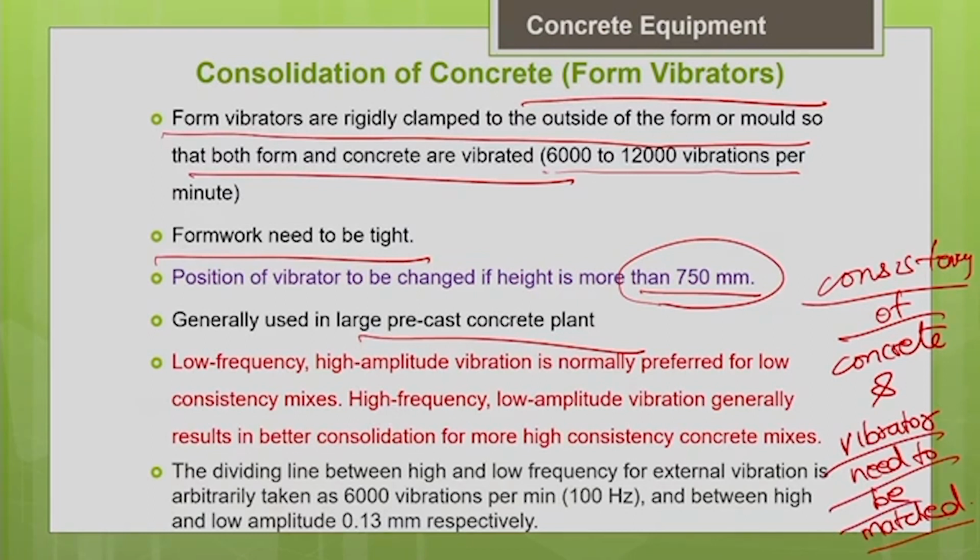Another important thing is the frequency and the amplitude of the vibration needed. That also depends upon the consistency of your concrete only, because that is going to govern the efficiency of your vibration. Basically, for dry mixes which have low consistency, obviously the spacing between the particles will be more, because there will be a lot of voids in the dry mixes. In stiff mixes or low consistency mixes, there will be a lot of voids. The spacing between the particles will be more.